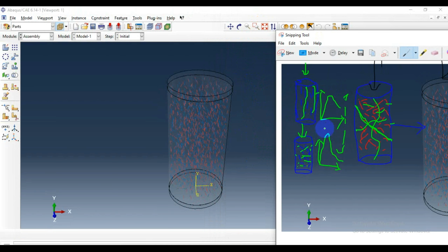But fiber orientation also impacts the thermal and chemical stability. Aligned fibers basically reduce thermal expansion in a specific direction, while random orientation may lead to more uniform properties across the composite, which is a good way to consider. Another thing is anisotropy. So FRC with aligned fibers exhibits anisotropic properties, which means that their mechanical behavior differs based on the direction of the applied force. This anisotropy must be considered in design, as the material may perform exceptionally well in one direction but poorly in another direction if you are considering homogenization.